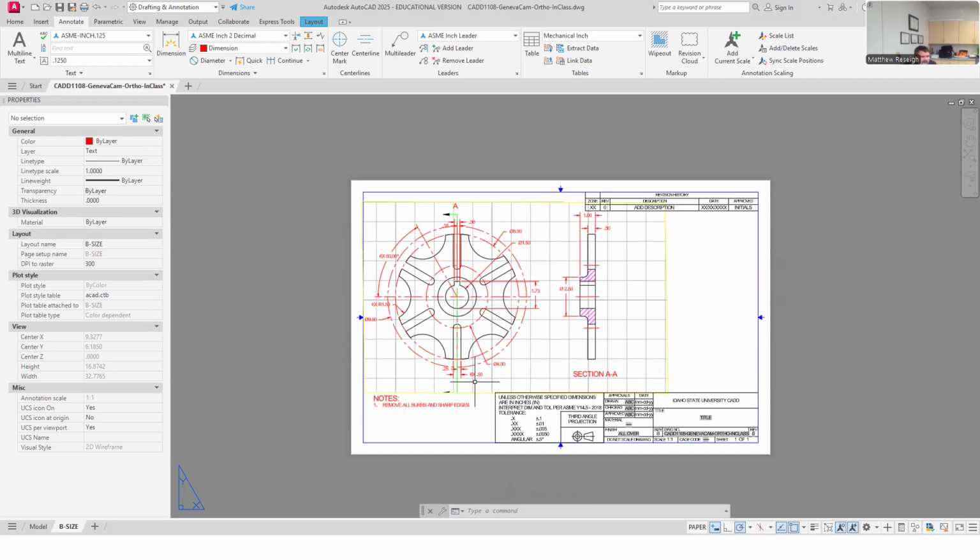There isn't a lot to dial in here. All of my diameter and radius ones can kind of stay. The ones I'm looking to fix are probably the slot width and the keyway width. Fix those, maybe just 3/8 off the last outer center line. Then I'll adjust my cutting plane line, and then I'll adjust some of the section view spacings there. But then this one should be pretty close to done. Line type scale, I can see it needs to be fixed a little bit. And I'll probably drop my whole viewport down a little bit away from my revision block.